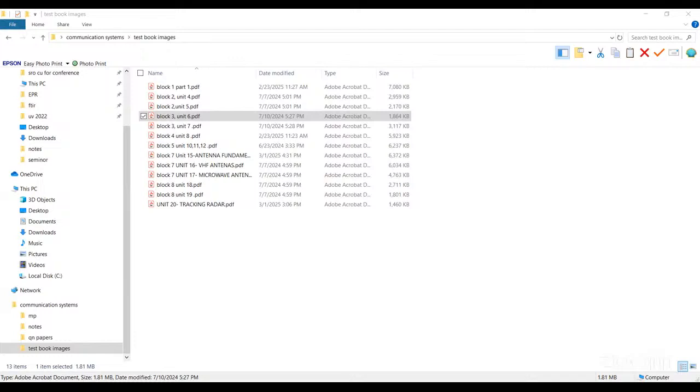Next, in figure number 6.2, we have the 2-hole directional coupler. What is this 2-hole directional coupler? On the first line, I have one waveguide, and below, another waveguide, but in between, a gap is there. When the line is transmitting, it will not go directly. It will enter into this one. While entering, whether it is moving in this direction or in the backward direction, we will concentrate. Based on this, we will categorize this into 4 parts.